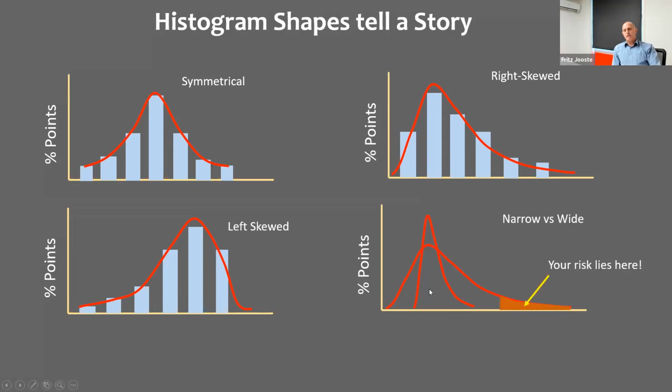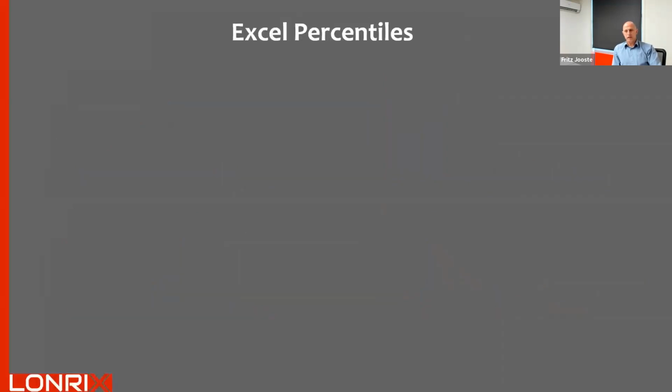So if you are doing, for example, deterioration modeling, and you are relying on the average predicted value for every treatment length or every segment on your network, you may be really badly bitten by this group of data that is lying over here that is not being included in your model at all. We hope to get into this territory later on this year with other webinars.